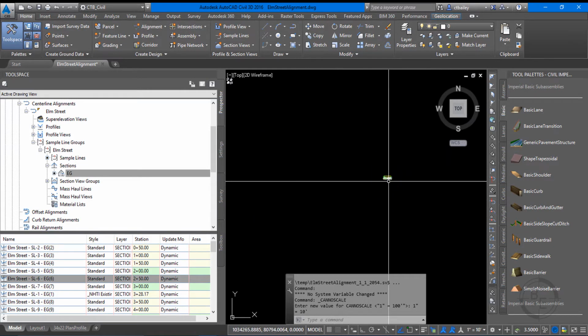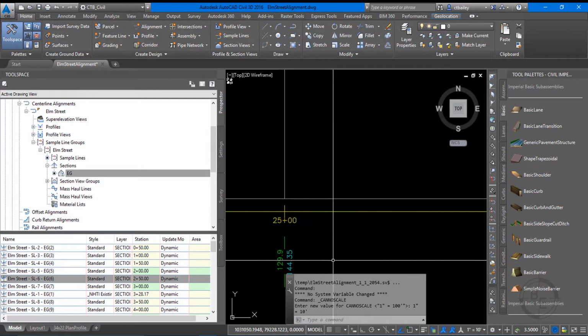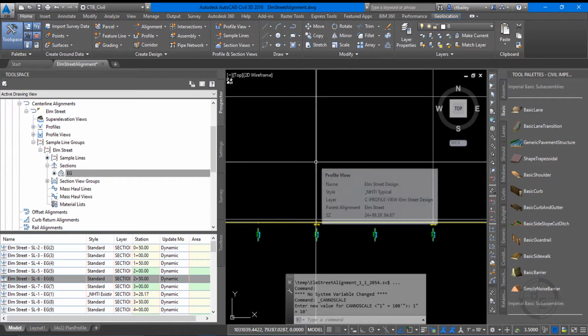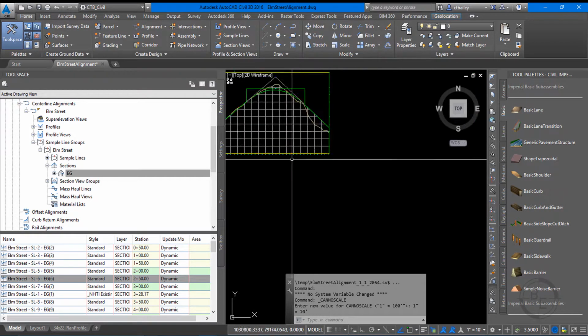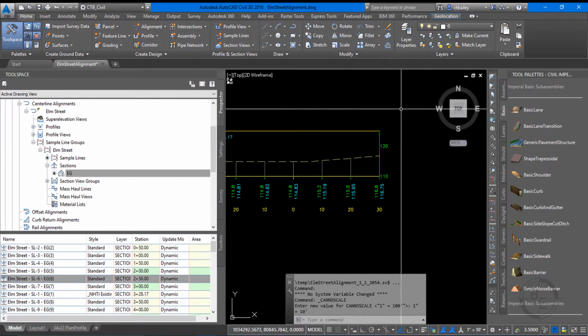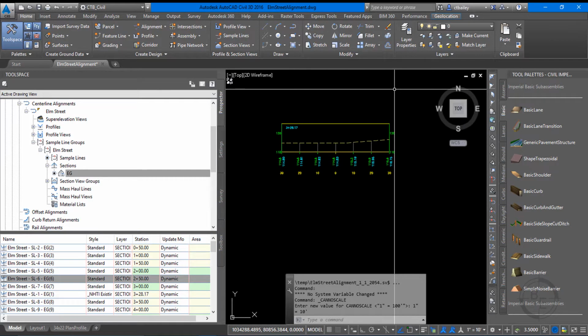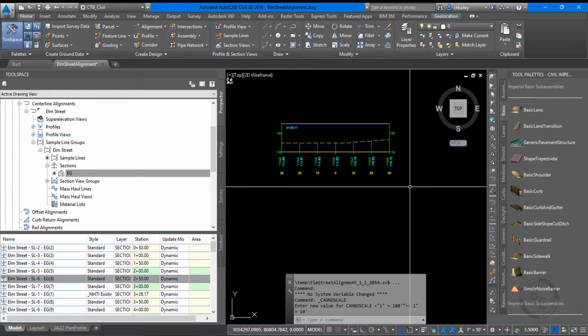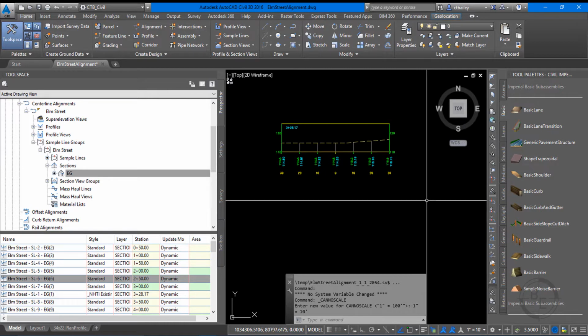Now, the problem, of course, you'll see is now everything else is all screwed up with our annotation scales, because this style was set up as a 50 scale or even 100 scale. When we do cross sections in industry, it's very common to have an entire drawing set up just for the cross sections, and it's okay at that point to lay down the annotative scale to the plotted scale of 1 inch equals 10 in this case. Now it is possible and very often done where you plot the cross sections in the same drawing, but it gets a little hokey in the model view. That's all.